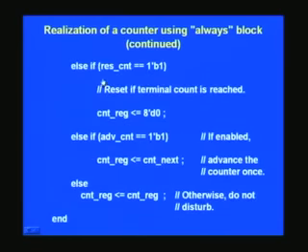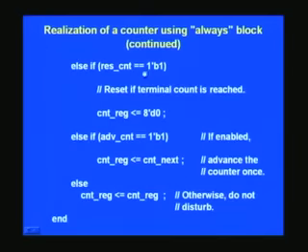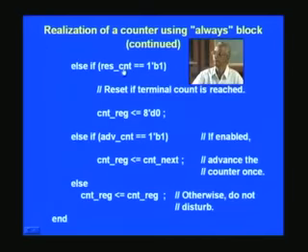So next what we need to do is, when the counter is 255, as we have already seen here, then reset, and that's what we are going to do here. So if it is 1, then reset the counter. This counter output receives a 0 signal here.